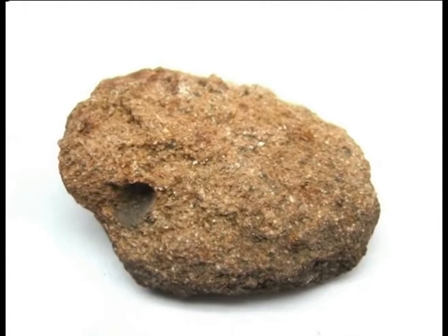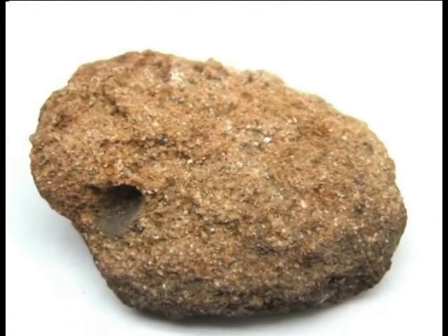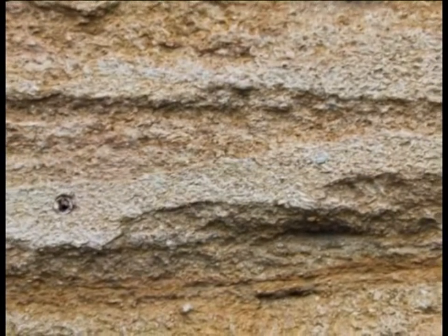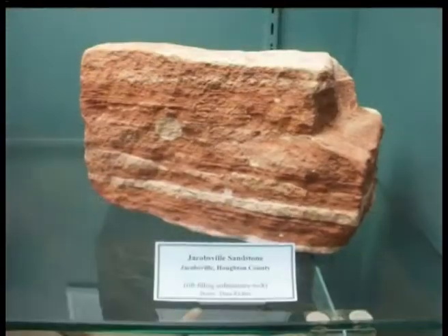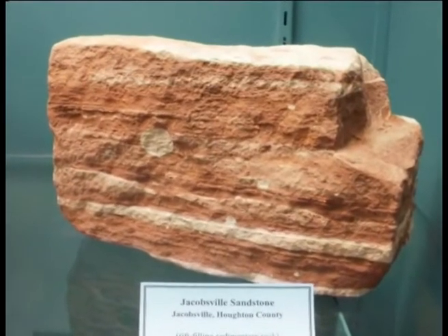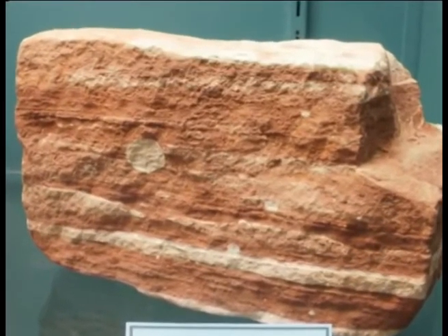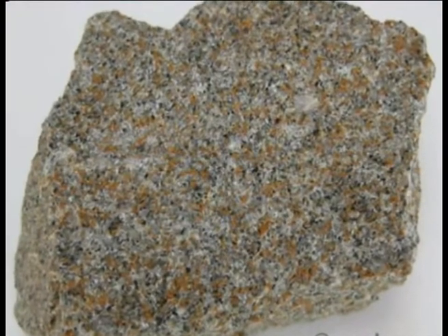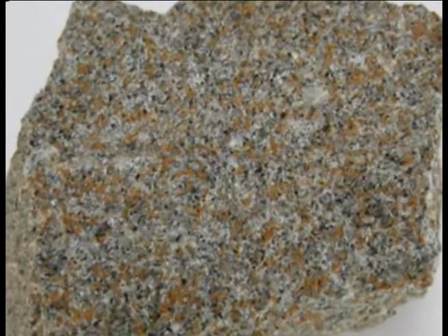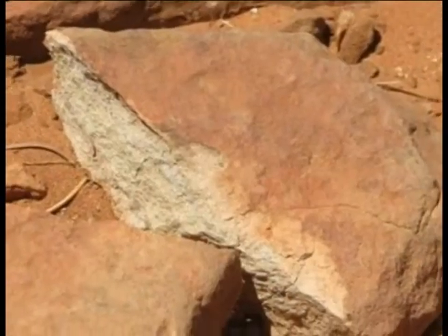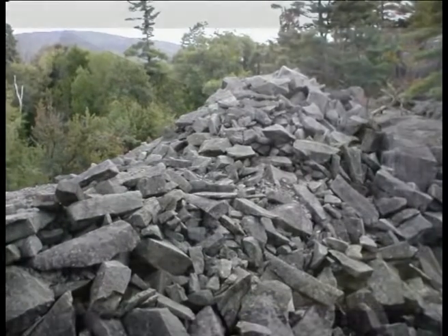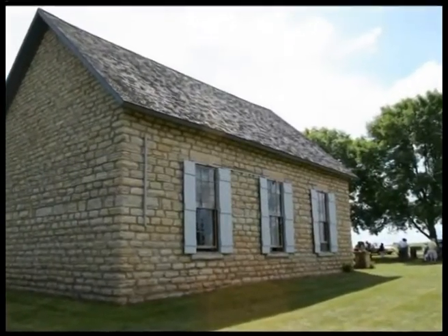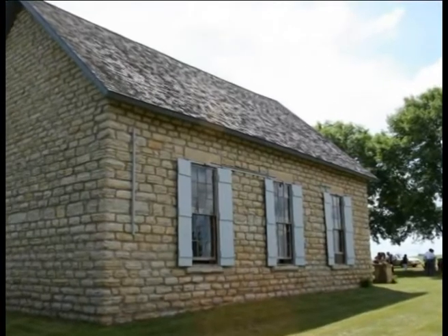Sandstones may show a very low crushing strength when loaded parallel to the bedding planes than when loaded perpendicular to the same structure. Except for sandstones, quartzite and some gneisses, most other sedimentary and metamorphic rocks are composed of clayey, calcareous and hydrated silicate minerals which are inherently weak in strength. Crushing strength of common types of building stones is generally higher than the loads that they are supposed to withstand in ordinary types of building constructions.